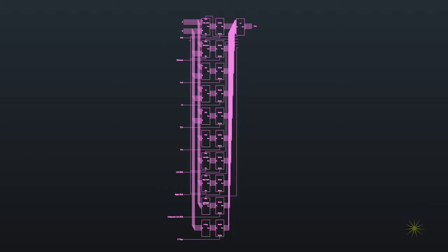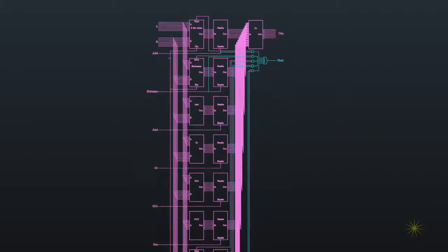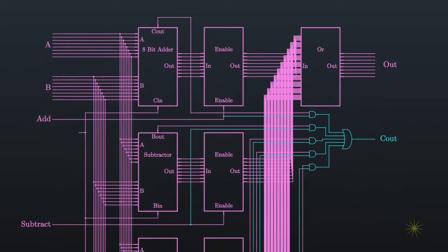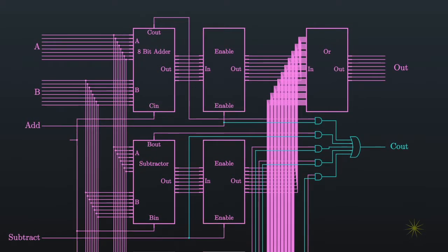Of course, some of our components have a carry output, such as addition or shift. We handle this by tying together these carry outputs the same way, with separate AND gates tied to the appropriate control lines, united with an OR gate. Sometimes we may want to add in the carry input to our system. Sometimes we may not. We handle this with our carry enable line.